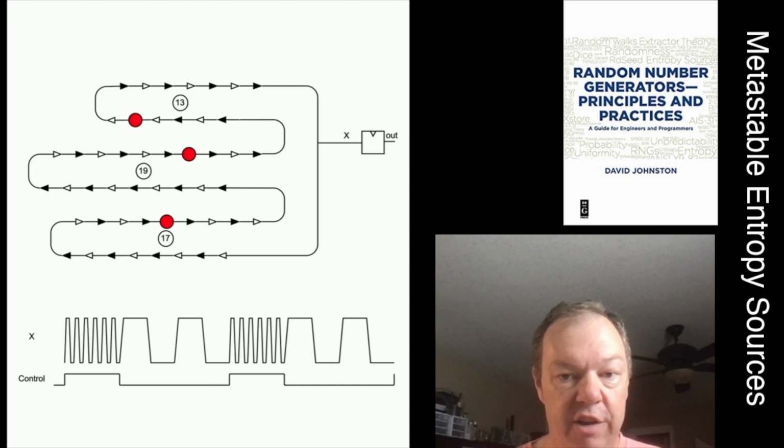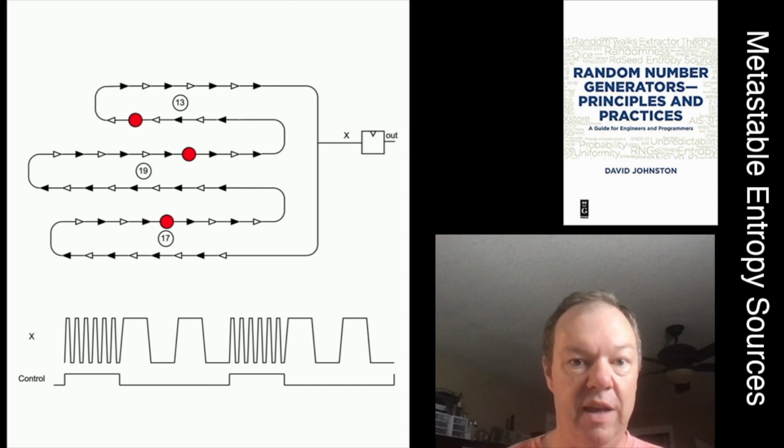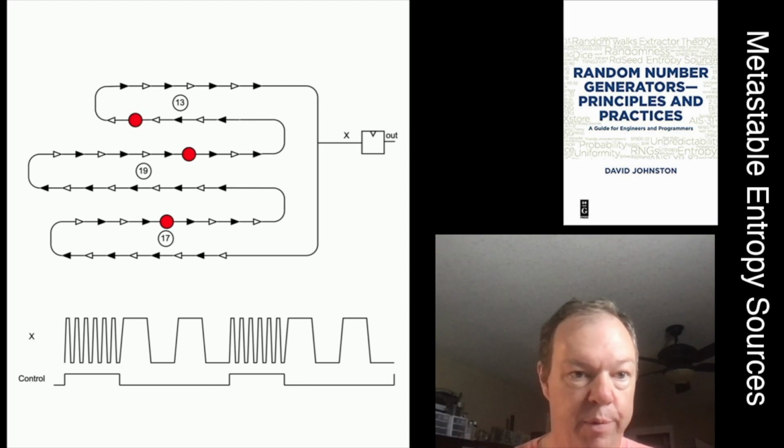They are generally the most reliable kind of entropy source, because metastability is guaranteed to happen in asynchronous systems, in digital systems, where you have any level of asynchrony and you're trying to sample data from one clock domain to another, it's going to happen. And here we're creating 3 clock domains and turning it into one. In the forced latch metastable resolver, we're forcing the single latch into metastability and letting the noise determine how it resolves, which is a fundamentally different structure.